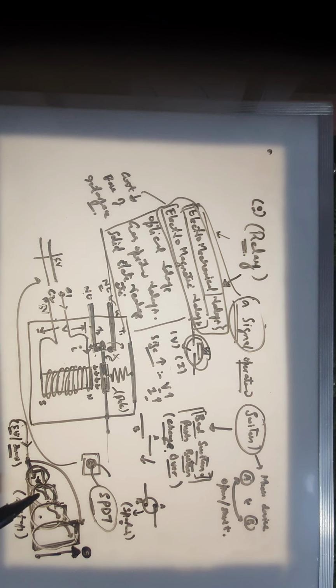So now we have already checked out the solenoid. Now we checked out the relay, and now we will have to see the driver that will drive this relay, because again there is a problem. We have reached a lower voltage, 5 volts, that will operate this relay, but your microcontroller can't provide the current that will get this relay on, because the relay will again take currents of the order of 100 milliamperes.